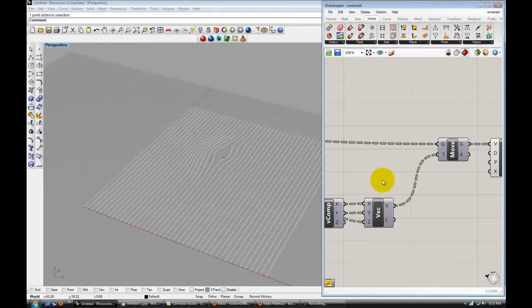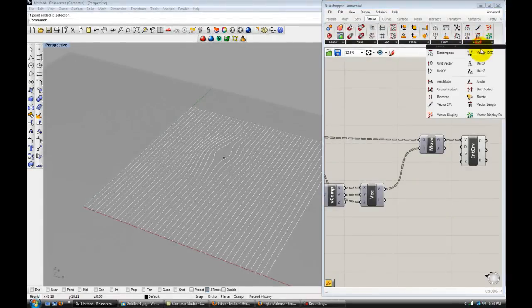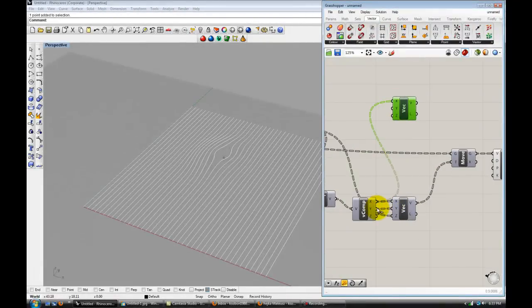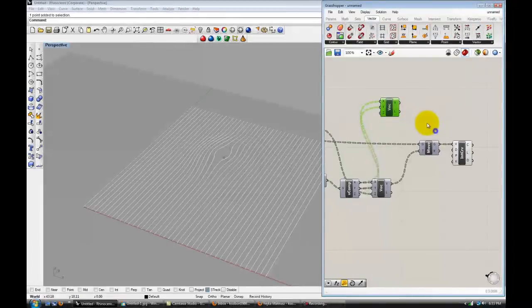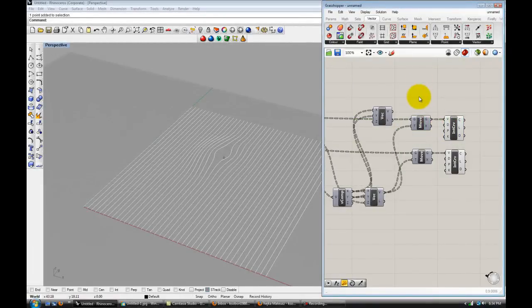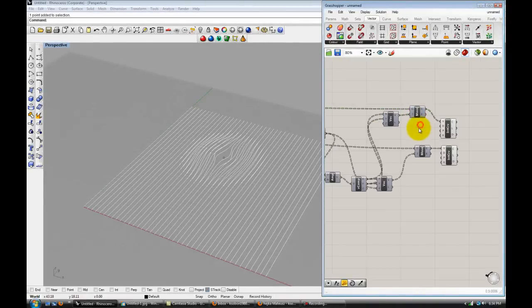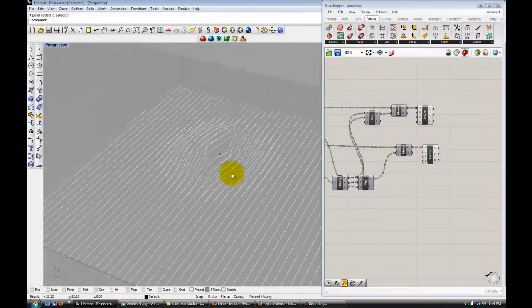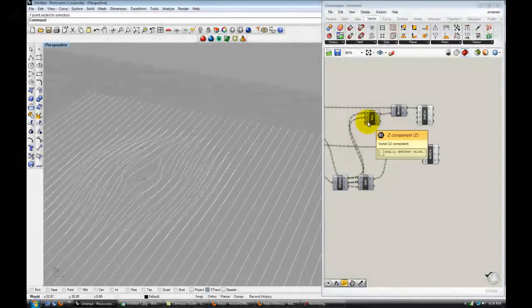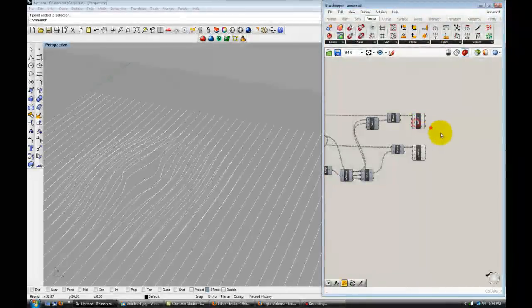So what we're going to need is a vector xyz for that. And just connect the x and y. We don't want a z, we just want a flat kind of projection. And I just Control C, Control V those, and for vectors, I'm going to create another set of lines. So what that did is it duplicated the exact same lines, but flat without z deformation, so they don't move up, they just kind of flat project what happened.